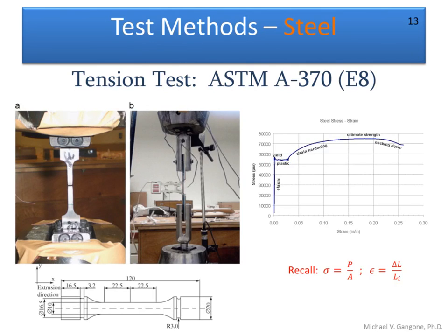And then something happens within the material at the microstructure level, where the atoms rearrange themselves so that the material starts to pick back up, and we get what's called strain hardening. Okay, so the material kind of gets its second wind, so to say, and it starts to harden up to a particular point, and then eventually it goes back down until we get to the point where the material fractures at the end.